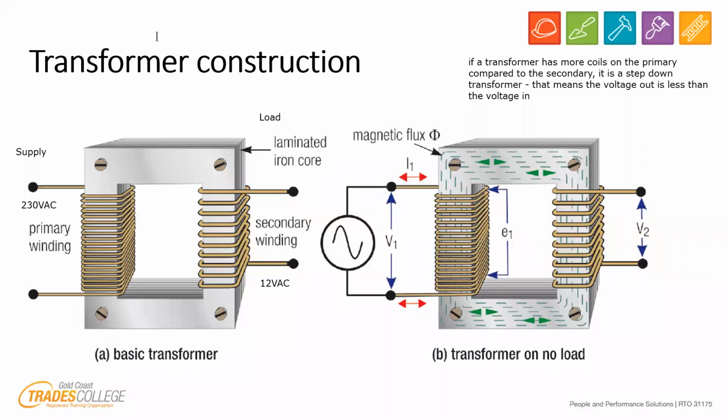What they do, and this is quite a good way of showing you, is that with a coil and a current flowing through it, you get a magnetic field. This magnetic field is going to be going up and down. We just looked at the sine wave going up and down as the magnet is spinning. This here is a sine wave.